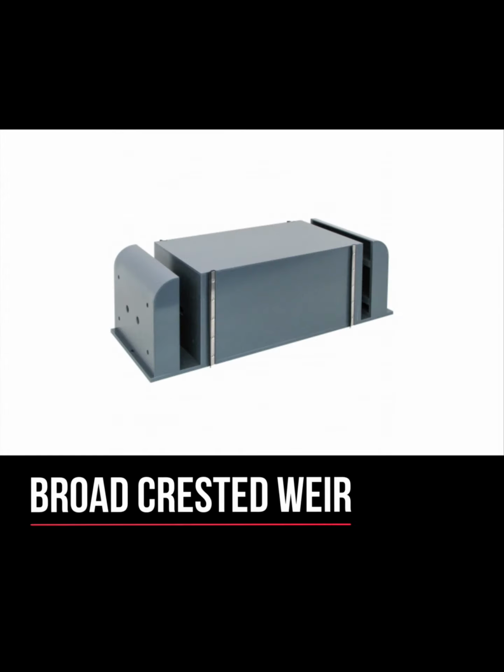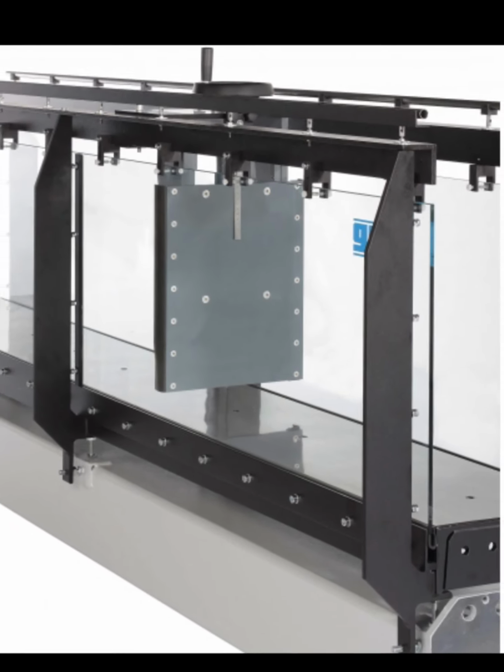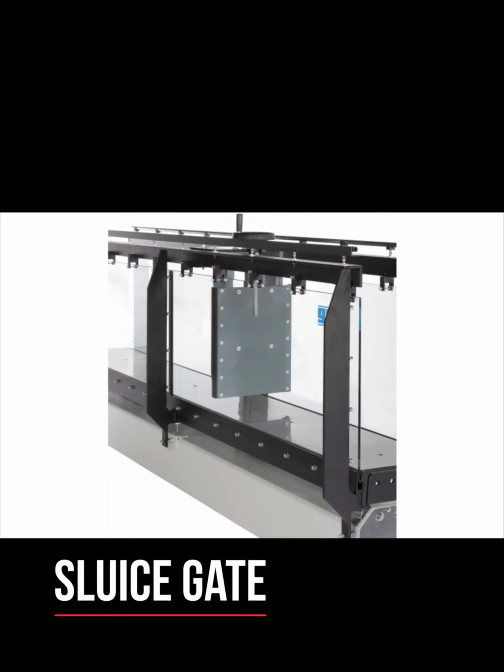This apparatus is called broad-crested weir, which is a type of weir, and a weir is a concrete or masonry structure which is constructed across the open channel, and they are commonly used for measuring the flow rate and also to prevent the flooding. This apparatus is called sluice gate, which is attached on the open channel flume. This device we use mainly for controlling the water level and flow rates in rivers and canals.